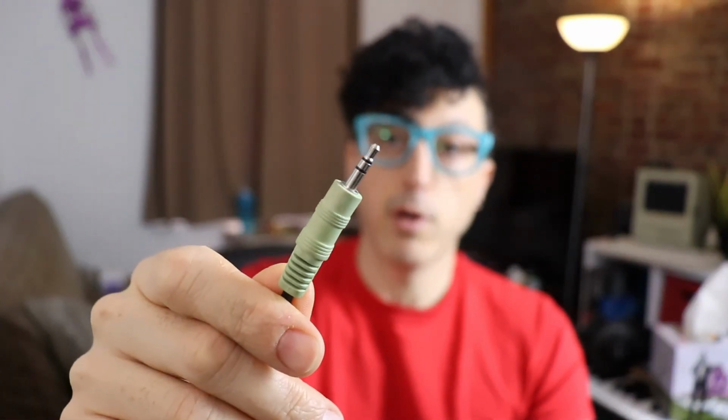There are a few things to consider. Some computer audio devices, like a lot of desktops, will have one input for line, one input for mic, and one output for headphones. In this situation, you'd want to use the line input, which will most likely take a plug like that, an 1/8 inch input. The reason you choose line over mic is that mic has a microphone preamp in it, which is not needed for the cassette player, since the cassette player already has an amplified signal.